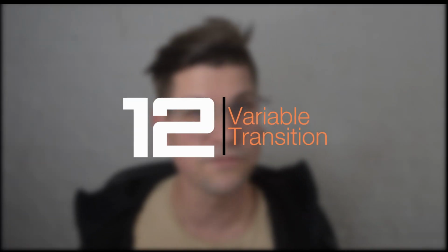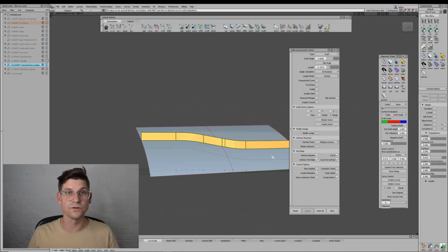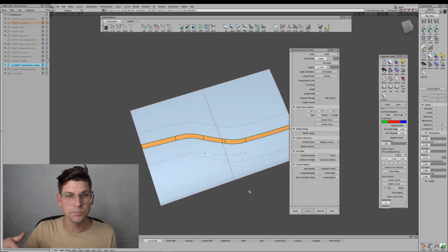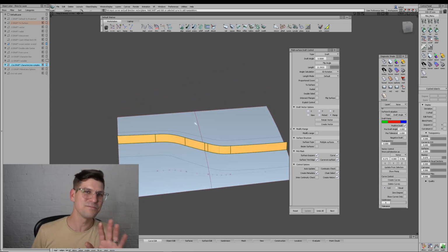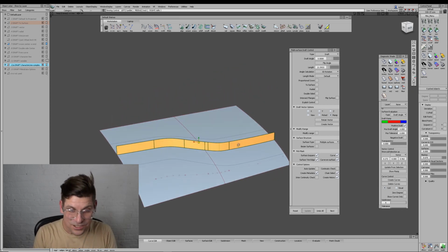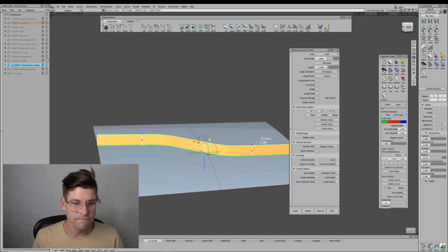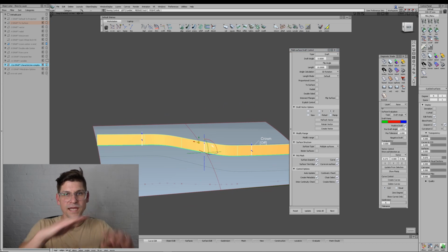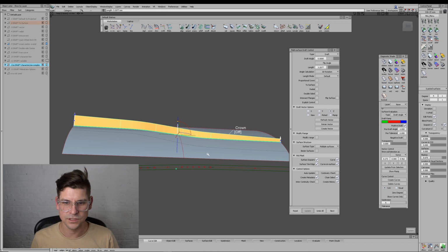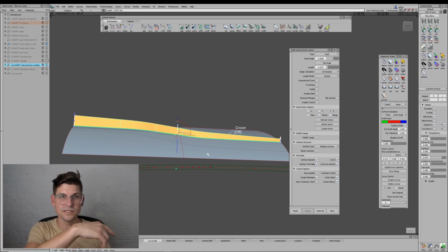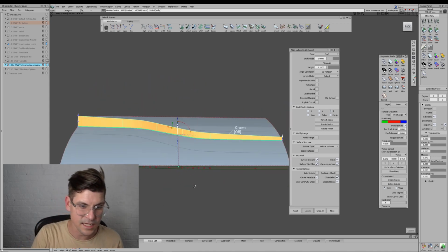Number 12 is using a variable over a complex shape. So here I'm in top view defining a pretty complex curve, or not really complex, but you know what I mean. And in addition, multiple surfaces. With the draft tool, if I had to make a linear transition from one side of this to the next, all I would have to do is bring these to the edges, and we'll just create one, drag one lower, and now it's a linear transition through this snake, this S shape.